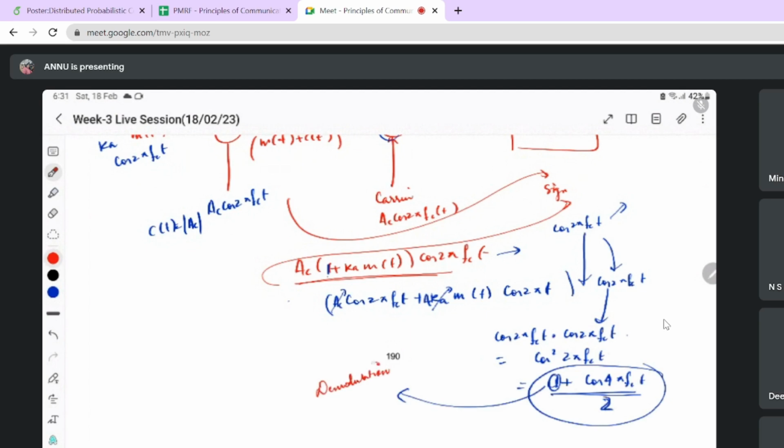So that's why during modulation we multiply with the carrier frequency, and during demodulation as well we multiply with the coherent, same frequency carrier, so that we will get a DC term, and that DC term will be passed out using a low pass filter. The low pass filter will be situated at baseband, and then you will get a demodulated signal. So let us see this using a proper diagram so that you will have the understanding. But the fundamental is this one, to remember how the demodulation occurs.